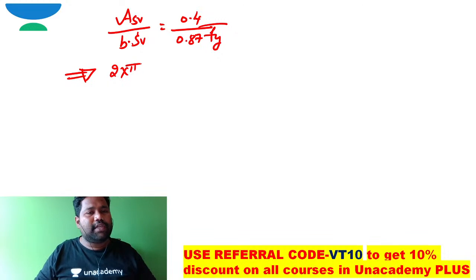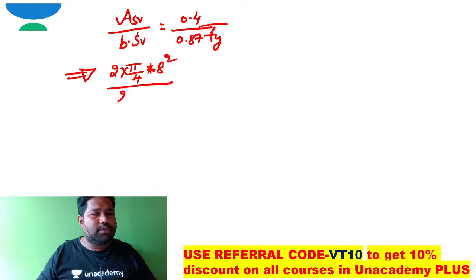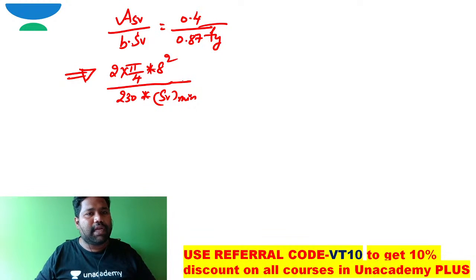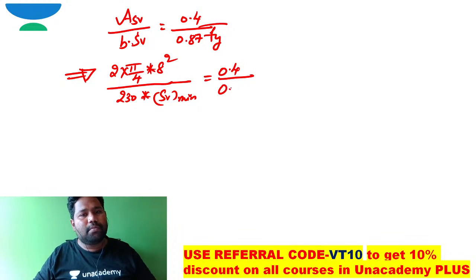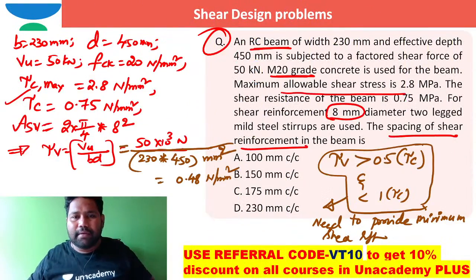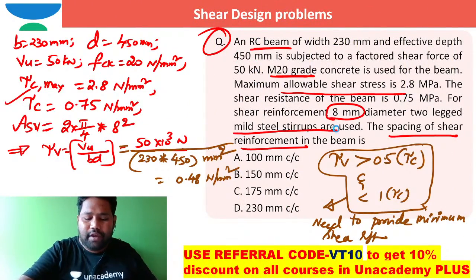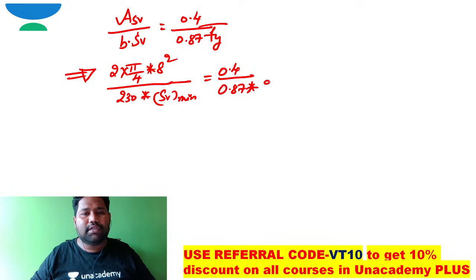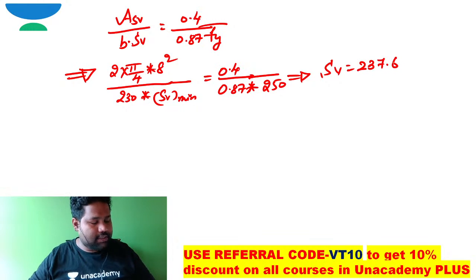So 2 into the cross-section area. What is the diameter of the single leg? It is 8 millimeters. So 2 into pi by 4 into 8 square, divided by B, the width of the beam, which is 230. This gives the spacing of shear reinforcement, Sv minimum. I can write 0.4 by 0.87 fy. What is the grade of stirrup steel? It was clearly given, mild steel stirrups are used. So from this I can work out Sv, which is equal to 237.7 millimeter.